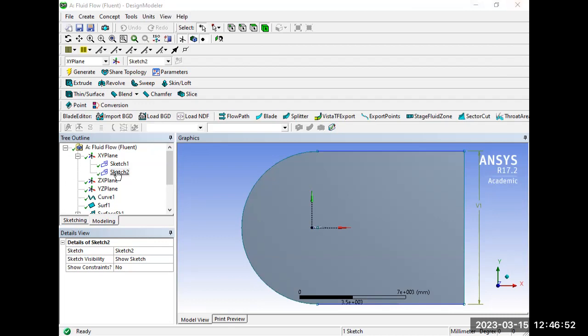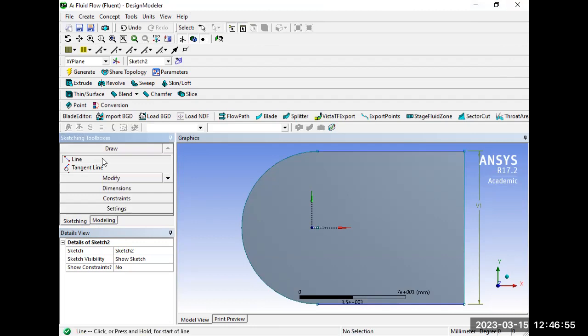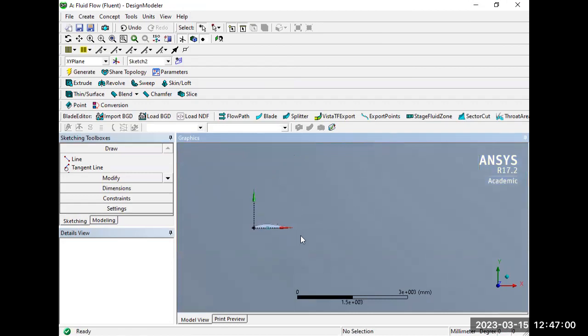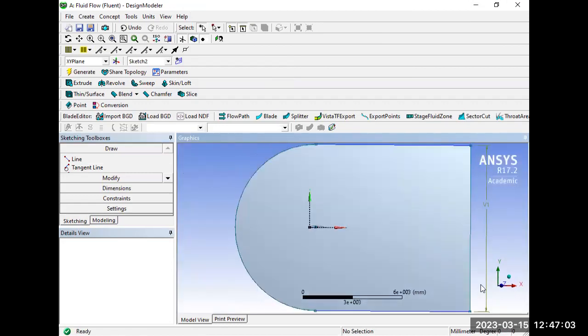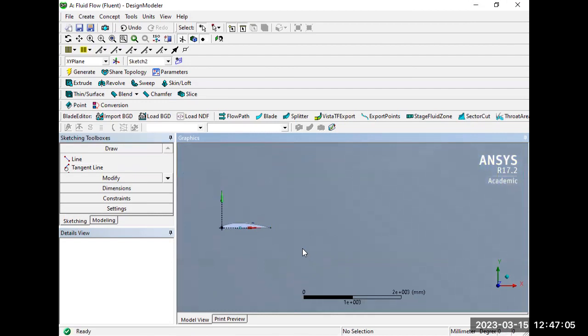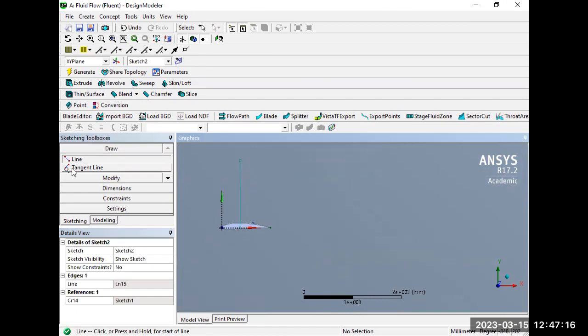Okay. So in sketch, simply go to sketching, line. When I'm trying to zoom in, from here I will simply draw one straight line. Similarly, again from here, I will draw one line in the downward direction. The point which you selected before, now you see one dot is mentioned here. From that dot only, I am pulling this line up.